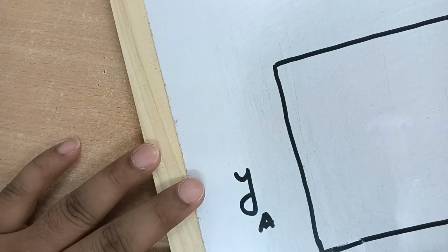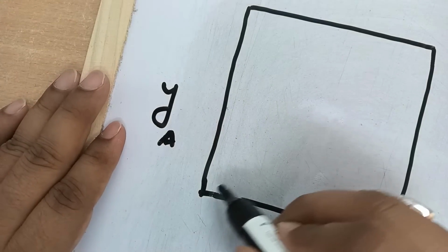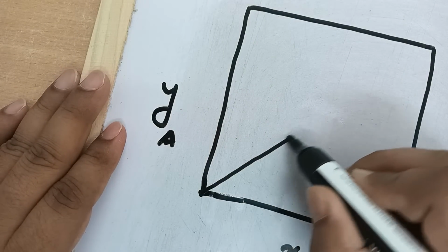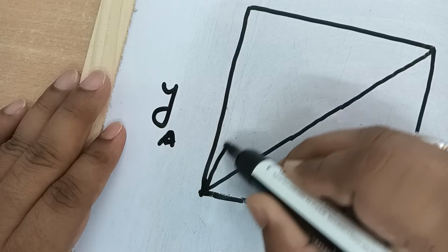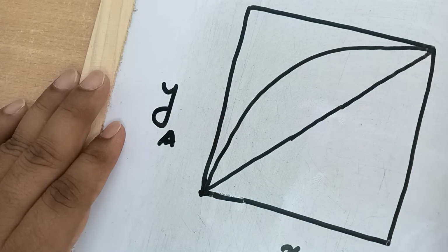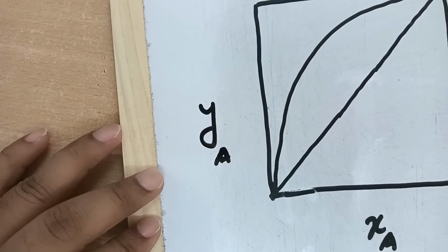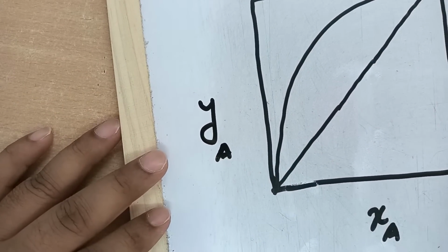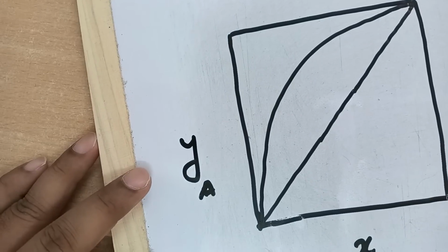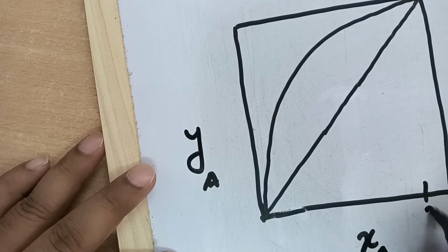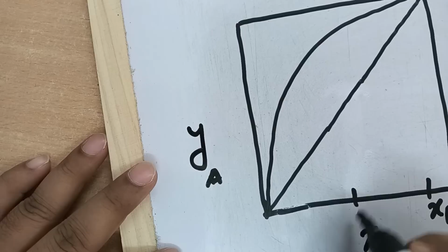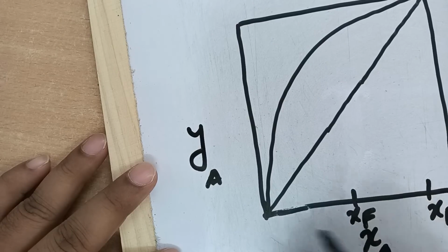A stands for the lighter or more volatile component, and then you have the y equal to x line. Then you draw the equilibrium line, the standard equilibrium line, which is concave downward. Fine. Now you don't know the value of the reflux ratio, so you cannot draw the enriching section operating line straight away.